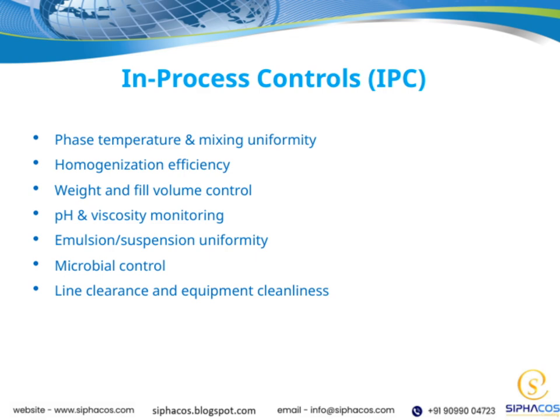Monitoring pH and viscosity is equally important, as these parameters influence product performance and stability, so continuous tracking helps us catch any deviations early. Emulsion and suspension uniformity are critical, especially for complex formulations. We need to make sure these are consistent to avoid separation or instability later on. Microbial control is another fundamental aspect. Preventing contamination ensures safety and extends shelf life.